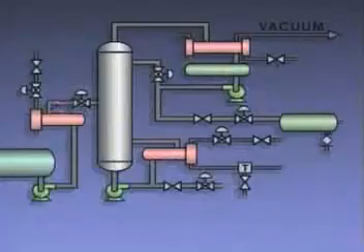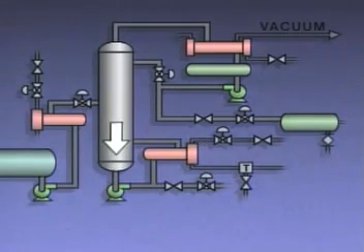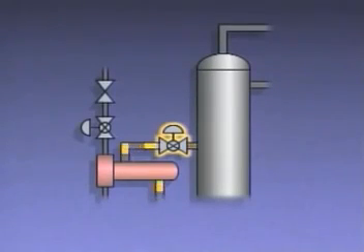When the vacuum in the column reaches the specified amount, preparations can be made to heat the mixture and begin the distillation process. In this system, the first thing that's done is to start the reboiler circulating pump. Starting the reboiler pump moves mixture from the bottom of the column, through the reboiler, and back into the column. Filling the reboiler with circulating mixture prevents it from being damaged when heat is applied. When the level in the column drops, the outside operator starts the feed pump. The feed control valve can then be opened as needed to feed the column.